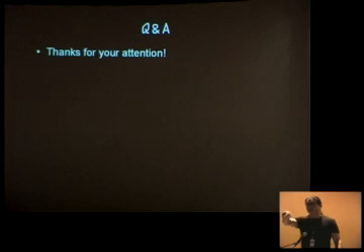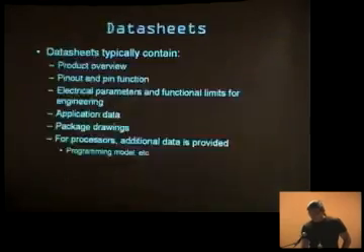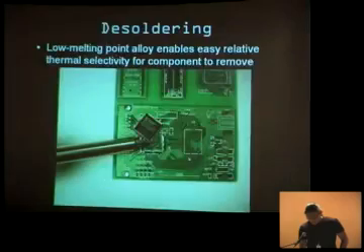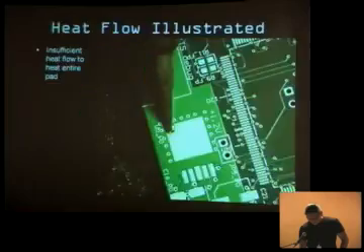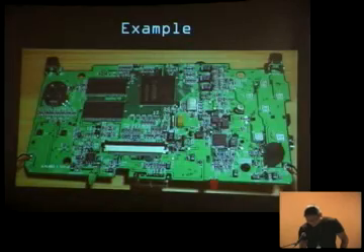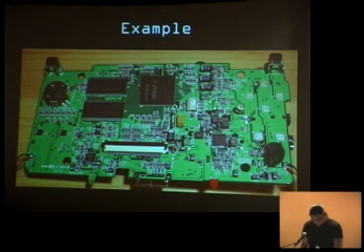So, over there in the yellow shirt? How do you find serial debug ports on a chip? Well, typically, for example with serial and JTAG ports, there's maybe some pictures here we can look at. This GP32X, I think, has one on it somewhere. Pretty sure it does. If you're looking at the processor, typically you can stare at it and guess a couple of things going on.